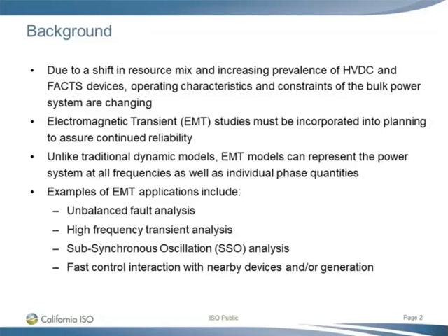So the traditional positive sequence model is no longer sufficient to cover all the study needs we have to maintain system reliability. Here we list some applicable studies where the EMT could be helpful, while the traditional positive sequence may not be sufficient.